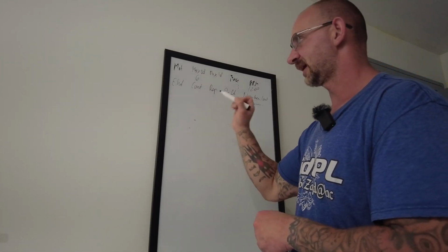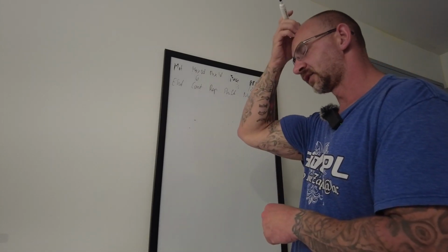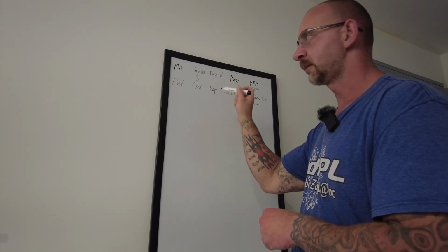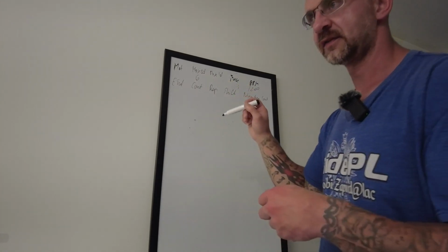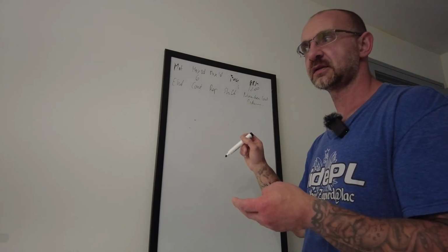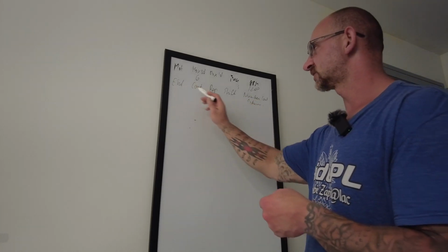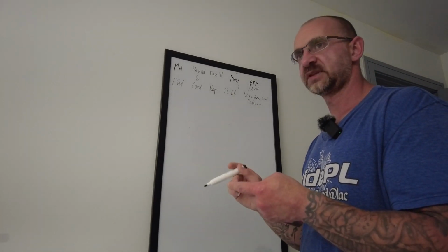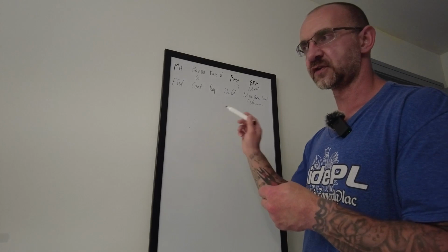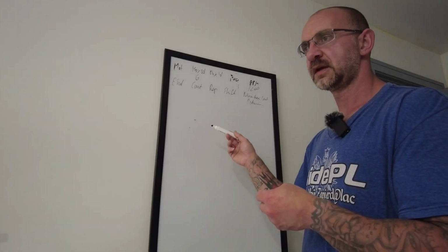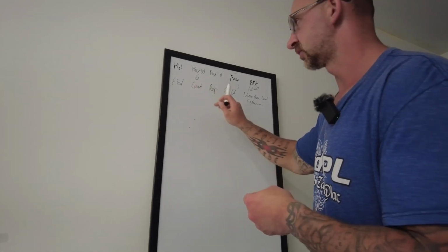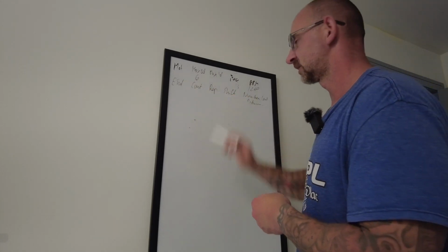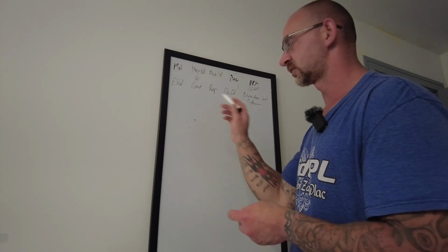As far as the end unit, technically every time your machine goes through a program, or if you're going to run trace or toolpath, she'll always look at the end. So let's say you have 10 units. If you run the first unit, second unit, for example, with single block, it's just going to run that unit. She's going to search for the end. If you're going to run everything in auto, she's going to look for the end.